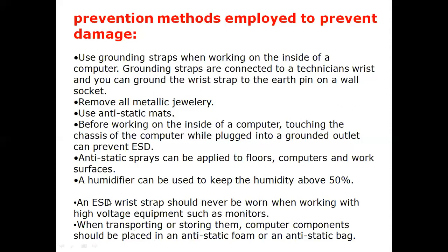An ESD electrostatic wrist strap should never be worn when working with high voltage equipment such as monitors. A monitor is an example of high voltage equipment. So whenever we are using an ESD wrist strap, we should not work with the monitor.